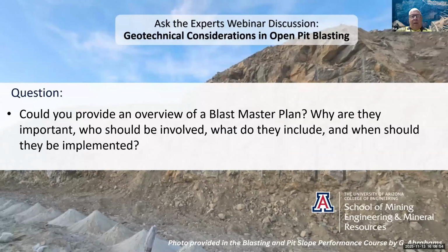Keeping in mind that wall control blasting, one of the key things here is it's all about that bench reliability to protect people from rockfall hazards and the like at the small scale. If the design is not being achieved, there are two options that we have. One is the operational performance needs to improve, or alternatively, if we can't do that, the design needs to be adjusted to accommodate it. So that's a good time to discuss that and what the TARPs are in place to trigger those decisions.